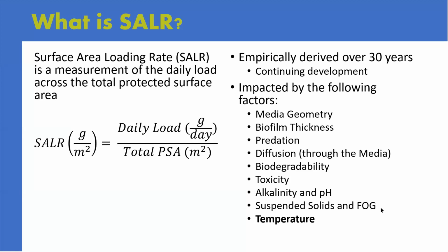Because your loading rate is basically saying, how much treatment can I achieve? And that's really dependent on your biology, right? And so the kinetics and the metabolism of your biology is going to be significantly impacted by temperature.